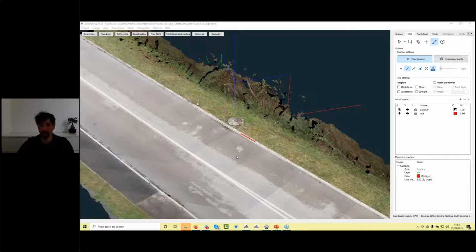but I would warmly advise you to invest a bit more and buy the Phantom 4 Pro, because there was a change in the camera. Phantom 4 Pro has already a 1-inch sensor, 20 megapixel camera, and what's more important, it has a global shutter. You can Google it on our website, what's the difference between global and rolling shutter. If you like to get accurate results and not use too many ground control points, definitely we would advise you to go with the Phantom 4 Pro. So not with the standard Phantom 4, Phantom 4 Pro.